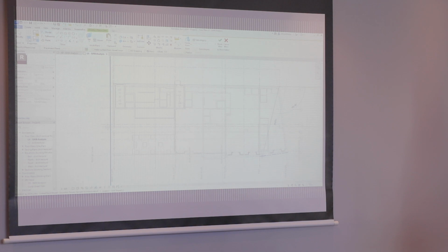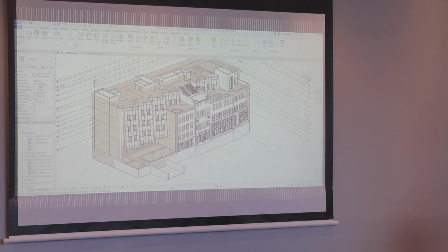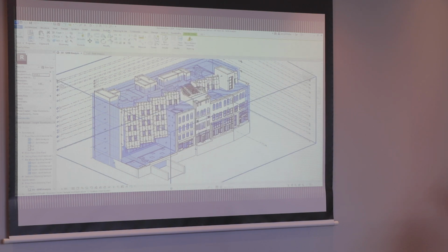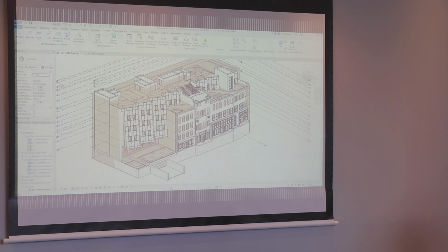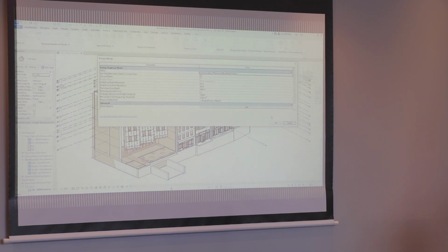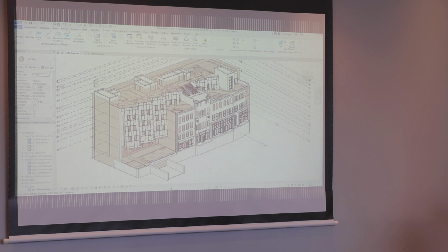And then using new features in Revit 24, it doesn't create an energy analysis model from everything in the model anymore. You can create it from views, you can turn things off really effectively. What I get left with is this mass over the form of the building that I can run energy analysis on, the conceptual mass, right? It's really, really simple, really high level, not a huge amount of detailed information. But the point is, that took me like 5 minutes, right? You know what I mean?